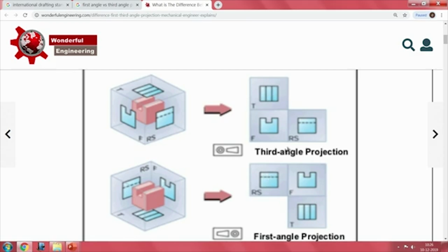In contrast, the third angle projection appears a little more logical, meaning this is a top view. You see what you see on the top and draw here. Whichever way you look at it, you draw here, and you will see a fully blocked thing, and then put dotted lines and then represent whatever you want.